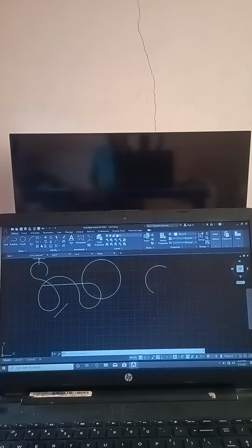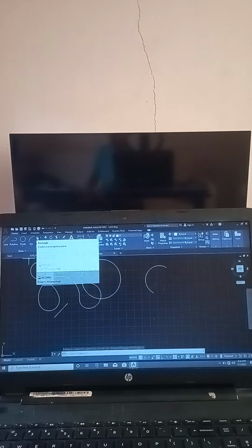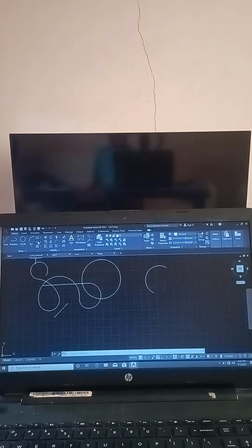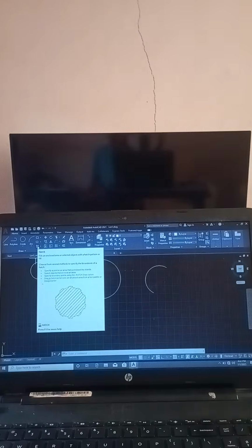So that is that. This one again, you have other things you can access beside. That is sphere or ellipse. You can click on it or you type EL, enter. That gives you ellipse. Then for rectangle, you can use the shortcut REC, enter. That gives you rectangle.